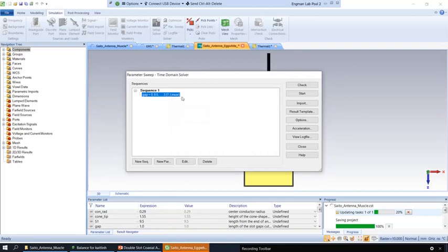So what does this really mean? What does this do for us? So what will happen is in CST Microwave Studio Suite, it will run a series of simulations varying the gap size. What you'll get, or what you'll be able to analyze, is in 1D results over here. Remember, we have something called S parameters. So S parameters, in the case of this antenna, we only have S11. S11 is a representation of the reflection coefficient. The reflection coefficient tells us how much energy gets reflected back to the signal or to the feed,